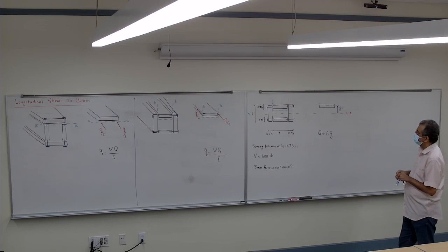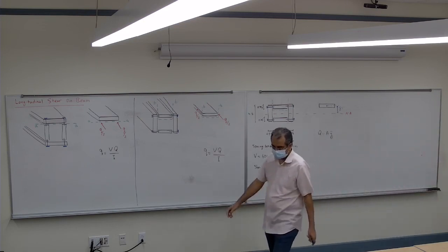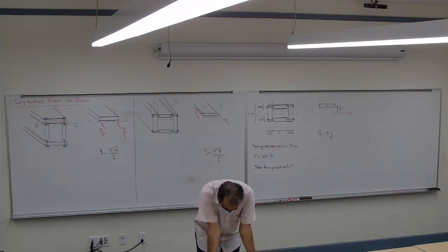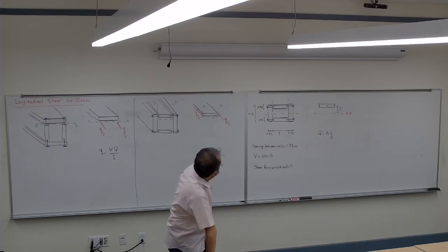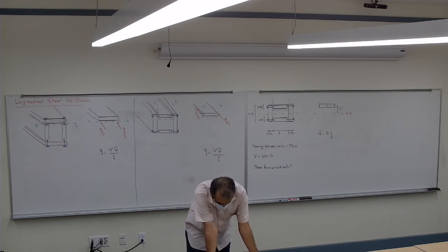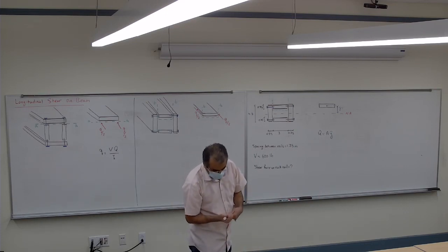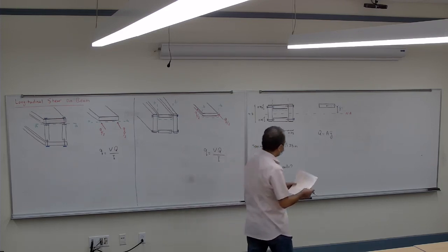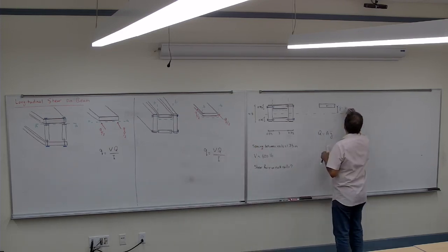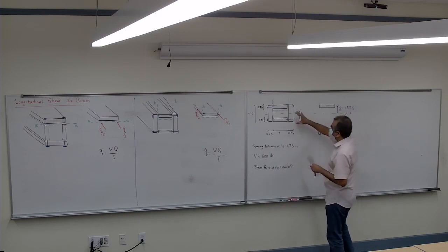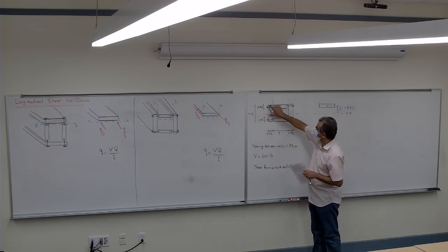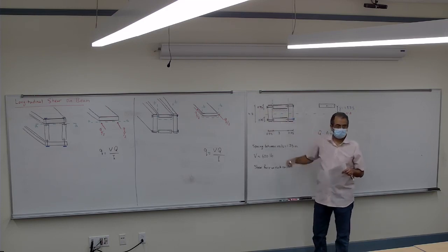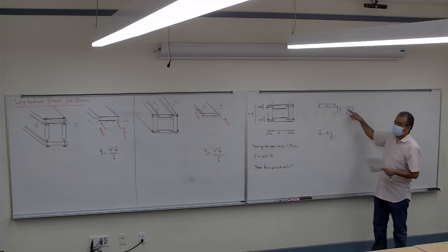2.25 minus 0.75 divided by 2. It should be less than 3. It's 1.875, because half of the height is 2.25, and then you take half of the 0.75 out of the 2.25. Is that correct? So that's the Y bar.